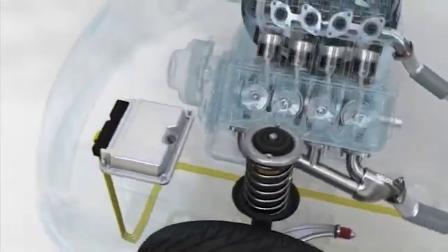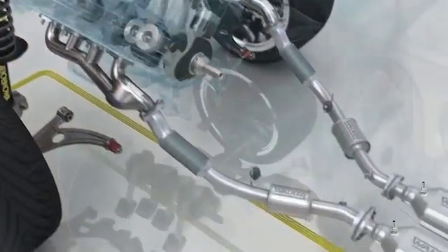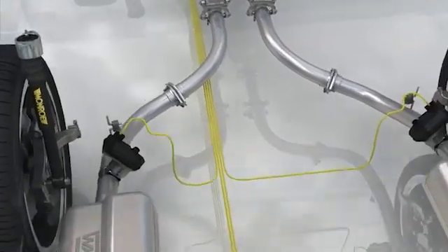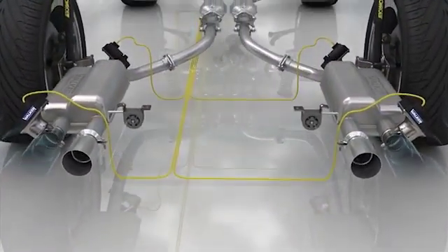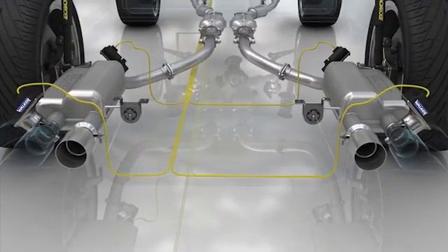The tailpipe valve is also controlled by the electronic control unit, ECU, of the vehicle. This, depending on the engine load condition, opens or closes the central disc to regulate the internal back pressure of the exhaust system, in addition to the noise level of the rear silencer.